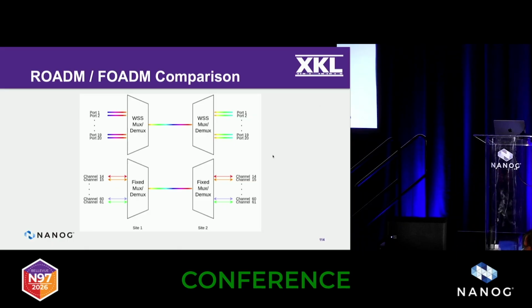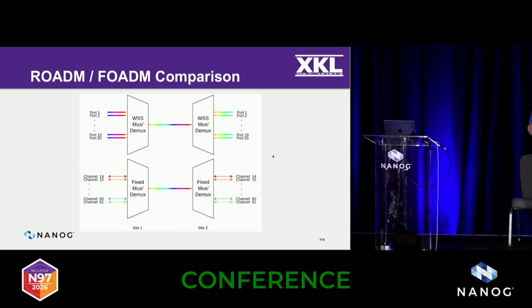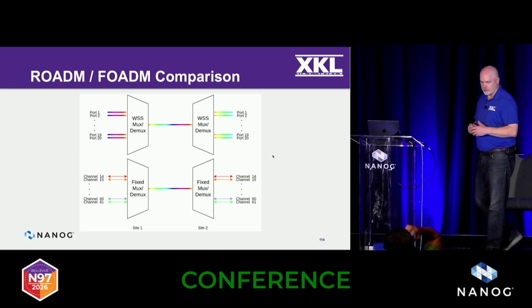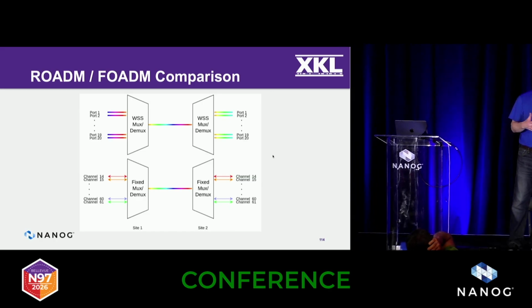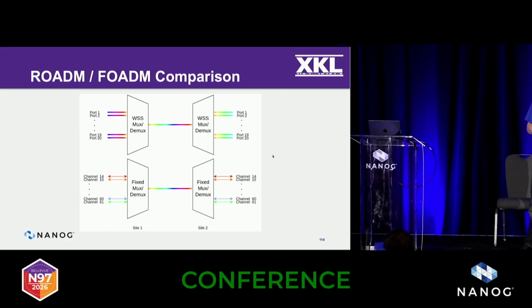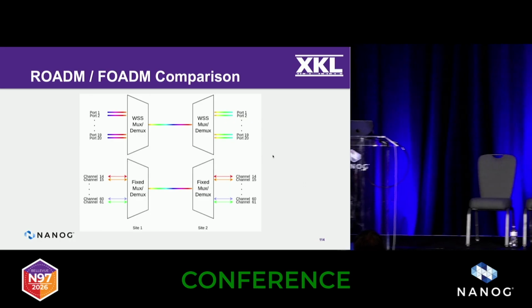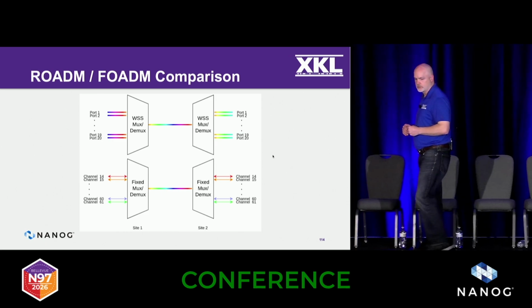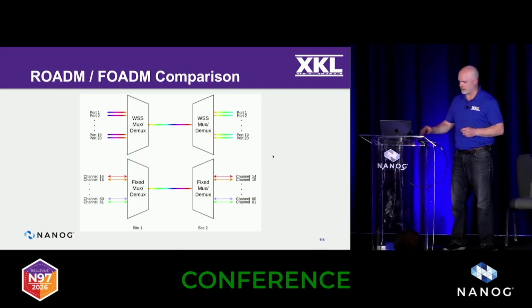So just a sort of a functional view here. The top design, that's your WSS, and the bottom one is your thin film AWG technology, the fixed stuff. Notice in the top guys, those are DWDM for all the ports. So I can send multiple colors of any frequency into the ports of your WSS. Whereas for the fixed mux demux, thin film, AWG, that's one color per port. So that's why it's drawn like that. You see the red, orange. So that's one of the main differences there.